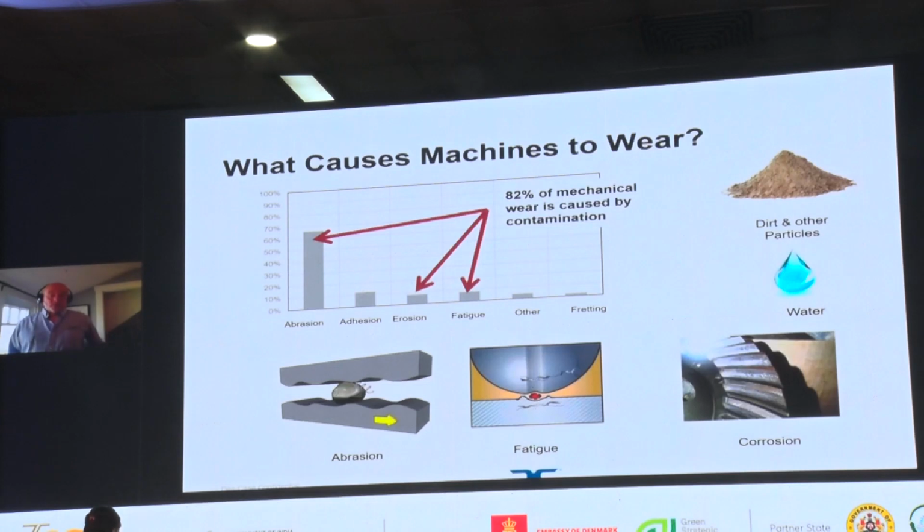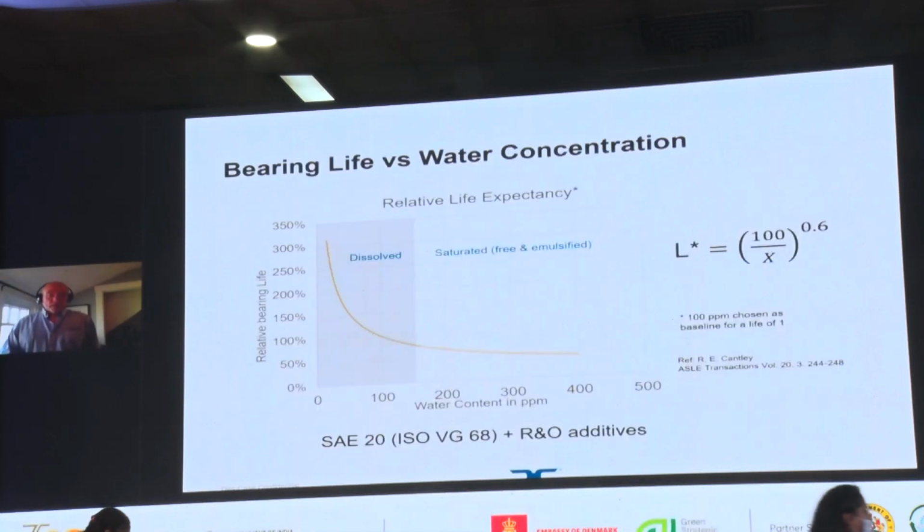So as that moisture enters, if the humidity inside the nacelle is very high, then the humidity inside our gearbox is also going to be pretty high, and that water can create problems such as rusting and corrosion. It does also impact fatigue life of bearings because water is actually, of course, a very poor lubricant, and it reduces the overall film strength of the oil. So controlling contaminants is critically important for achieving optimum reliability for wind turbine gearboxes.